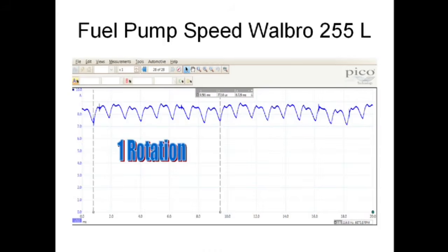If you're not sure that the pump you're working with is an 8-segment armature, where you're trying to figure out what is one rotation, study very closely the pattern observation, the humps. It kind of resembles McDonald's golden arches. Look for a uniform count where the shape of the armature, the kind of M shape, is repeating itself. There's a possibility you have a 6-segment or a higher than 8-segment pump, but the majority of them seem to fall into the 8-segment.